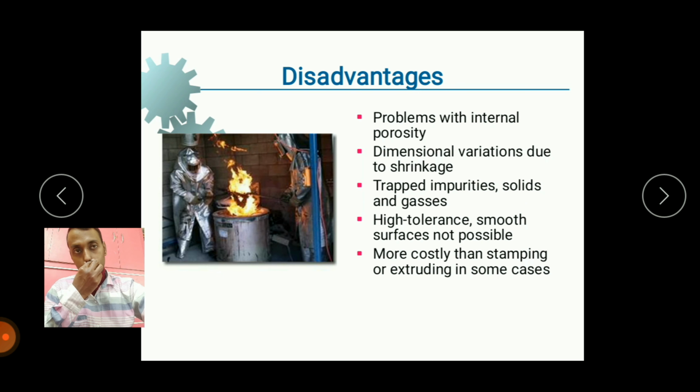Some disadvantages also. Problems with internal porosity, dimensional variation due to shrinkage, trapped impurities, solids and gases, high tolerance and smooth surface not possible, more costly than stamping or extrusion in some cases.